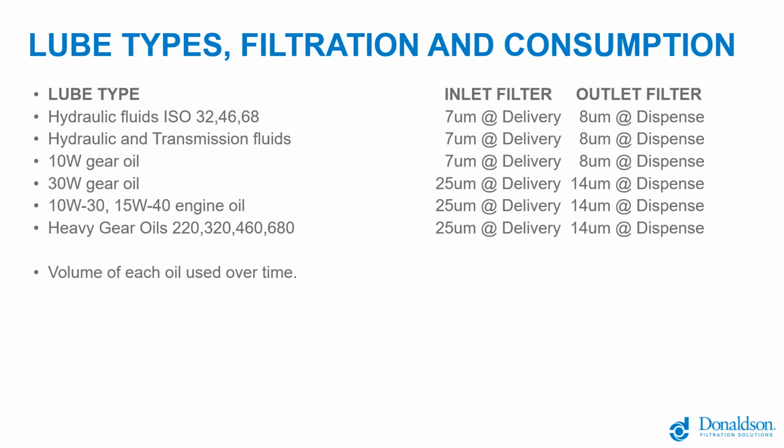And then it's important to consider the volume of each fluid used over time. That's important because there's new dirt coming in with each load of fluid, and you want to make sure you're sized correctly if it's a very high volume oil user. As an example, a mine site will use many times more fuel than they do oil, but a manufacturing plant where they're building mining equipment will use a ton of oil and very little fuel. So you kind of just need to get an idea to size for capacity based on the volume of fluid.